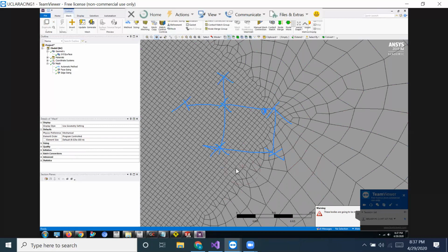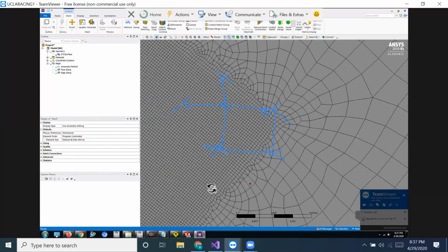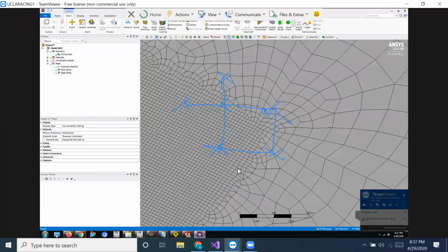So it's sort of gotten slightly better, but because it's kind of a weird flat panel, usually you try not to have such a drastic decrease in size. But yeah, it's slightly better, I think. So you can see that it's sort of gotten bigger and longer over here compared to over here. It's smaller and the sizes are slightly weird, but they also started putting triangles in there. Okay, but yeah, so usually you want to try and gradually decrease the mesh size, but in my opinion, it doesn't really matter that much. But yeah, it's a good practice to do.